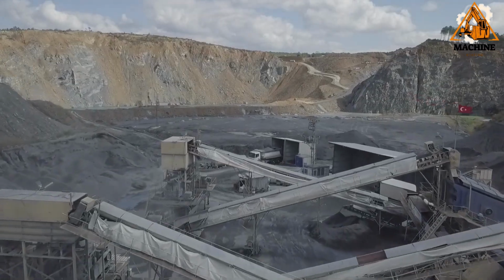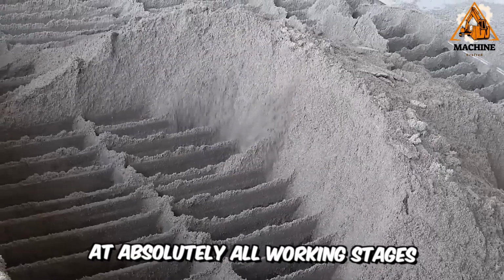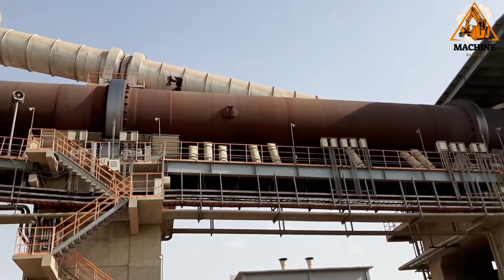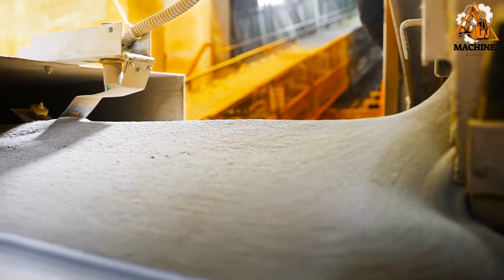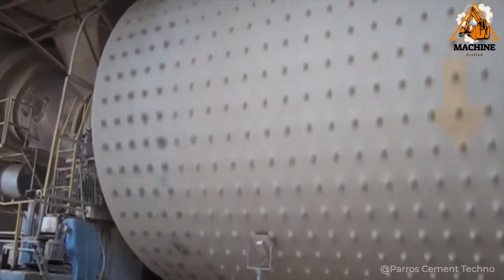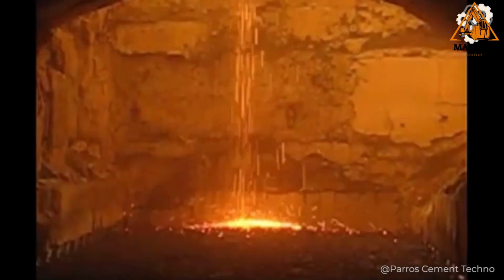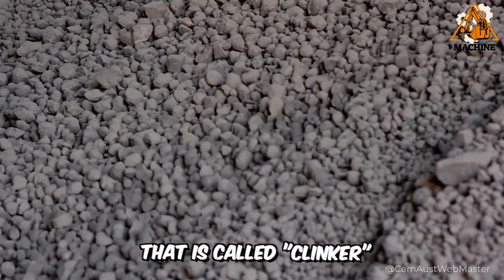What are its peculiarities? Firstly, it's the dryness of the components at absolutely all working stages. The basis of material production is based on the chemical and physical characteristics of the raw materials used. Each of the elements is necessarily subjected to an additional drying process and then ground to powder. The components are combined and mixed, or more scientifically, homogenized. The output can then be homogenization silage or raw meal, which is sent to the kiln to undergo a delicate roasting process. It is this fired material that is called clinker.